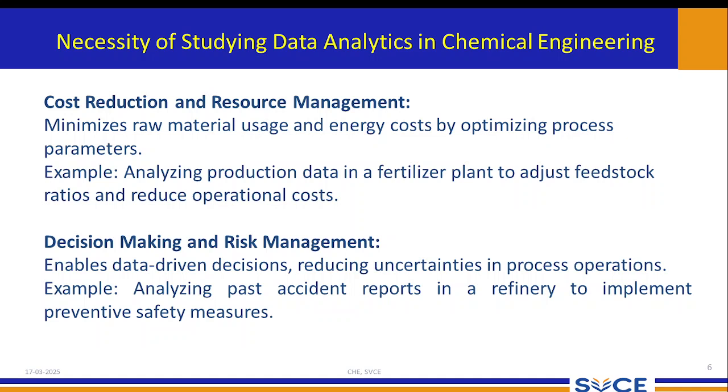And coming to the next point, decision making and risk management. It enables data driven decisions, reducing the uncertainties in process operation. If we have a lot of data, we will know when an issue arises. For example, if the pressure is 4 bar, fine, the system can withstand up to 7 bar. If the pressure becomes 8 bar, what will happen? Obviously, there may be chances the material of the design would not be able to withstand the force exerted by the pressure. Obviously, there may be chances of blast.